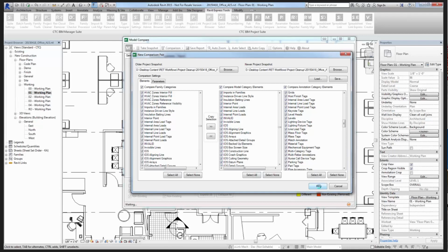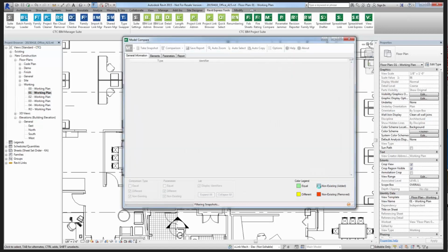If I'm in my model, if I'm, say, an electrical engineer or electrical contractor or mechanical, whatever, it doesn't matter, and I have somebody else's model linked into my file, when I snapshot my file, I get to find what's different about that link as it relates to my model. For example, what path was it last loaded from? Is it room bounding or not? Has it physically moved? Has it been pinned or unpinned? I can find that out. What work set was it on? That's information that I can compare back and forth, and I can compare both the type and instance work set. That's all stuff I can find out.